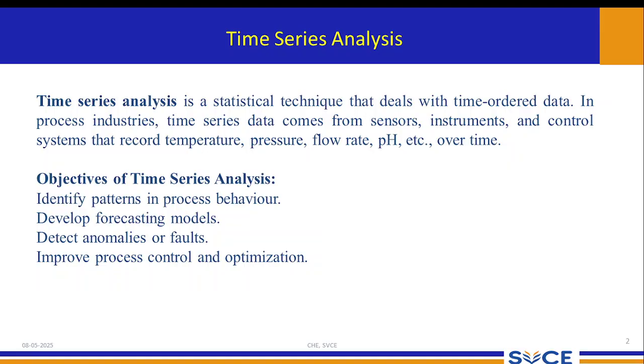The objectives of time series analysis: identify the patterns in process behavior, develop forecasting models, detect anomalies or faults, improve process control and optimization.